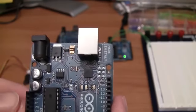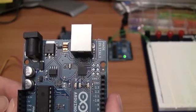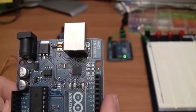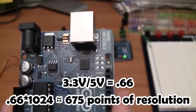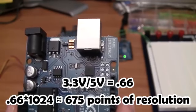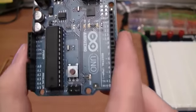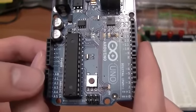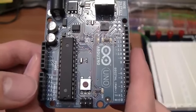You might want to consider using an external analog reference if you're only using sensors that go from 0 to 3.3 volts on a 5 volt Arduino. The reason for this is that the values from 3.3 volts up to 5 volts, if you use the default 5 volt reference, will basically be excluded and you'll be getting less resolution than you potentially could. Using an external voltage reference allows you to eliminate that problem. Down here on the bottom we can see the analog inputs, A0 through A5. There are 6 inputs available on the Arduino Uno.